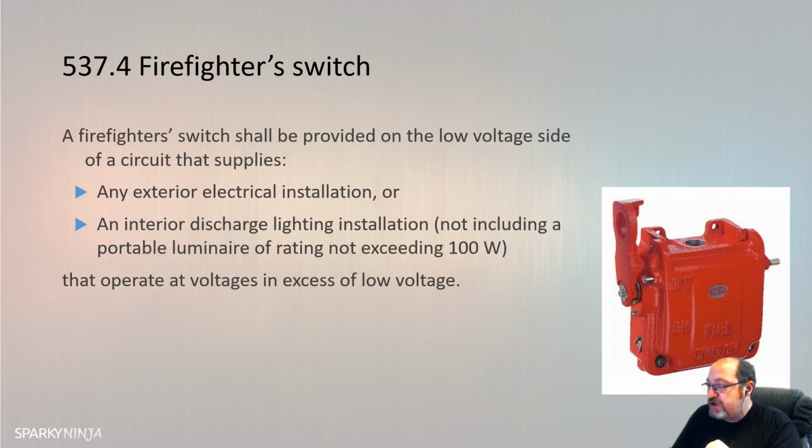Every outdoor installation on single premises should, wherever practicable, be controlled by a single switch. Let's think about the firefighter for a second. They want to go to one point. Similarly, every internal installation in each premise should be controlled by a single switch, independent of the switch for outdoor. They will comply with the following requirements where applicable.